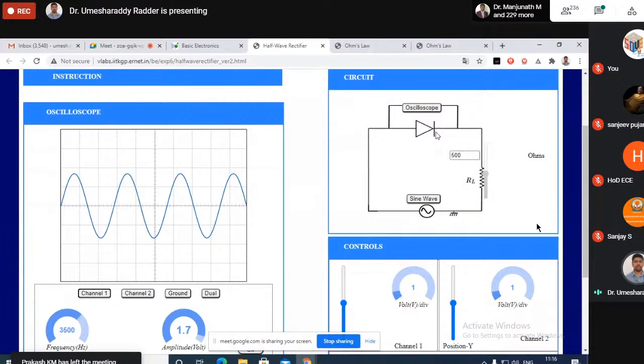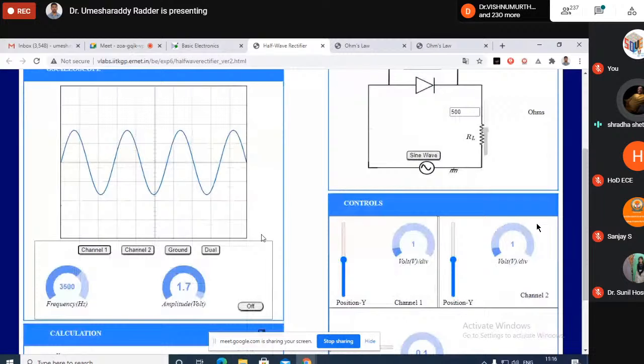Excuse me, madam. Here, by default, maybe a silicon diode is taken. I think maybe. Yes, sir, it is a default diode. Madam, if we have rigged up the circuit here in the lab, but I have made a wrong connection, I wanted to undo it. Correct, sir. Yes, it is possible. You can click on that node.